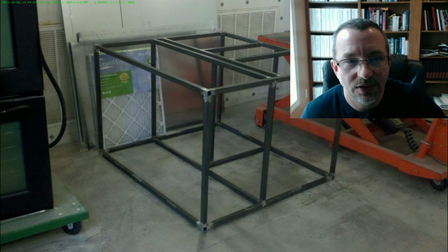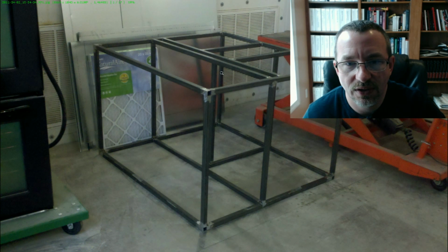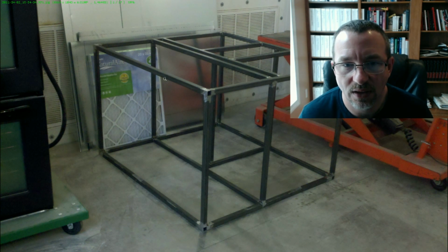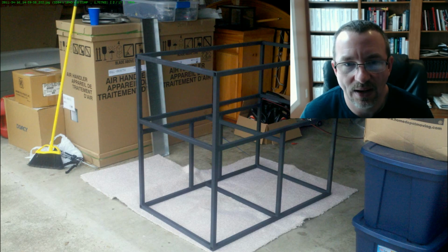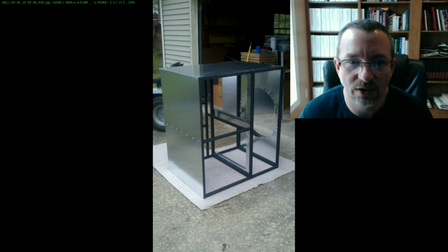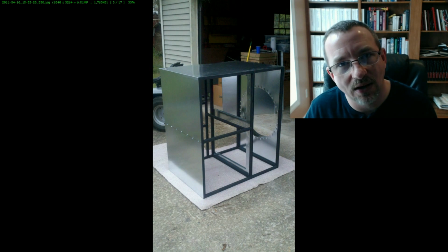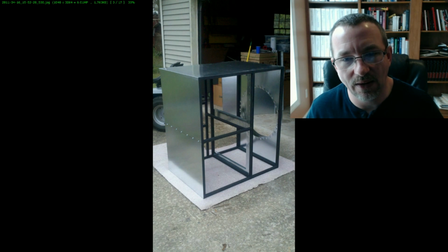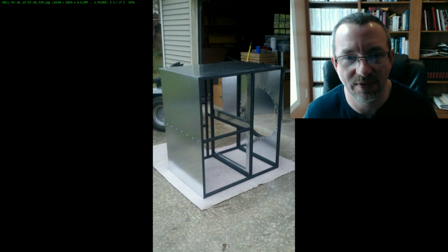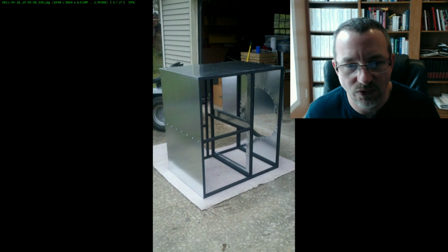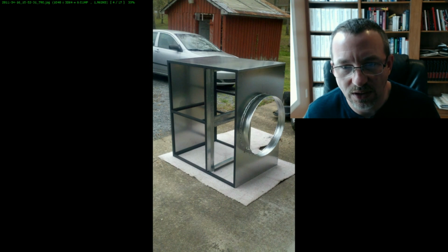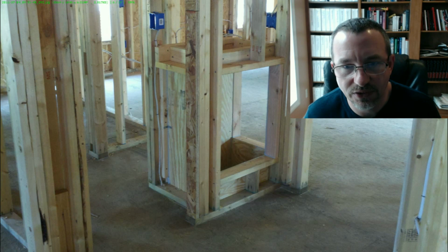So a couple pictures I took back from when I did the construction. This is the metal frame. I made it out of 1-inch square steel tubing, welded it together. This is the frame after I painted it, and the frame that we're looking at here is the actual return air. You remember that box that we saw in CAD right underneath the air handler? So the 2 air handlers set on top of this thing. So this is it while I was wrapping it in sheet metal. This you can see on the end is the 24-inch opening for the return air for the whole house.